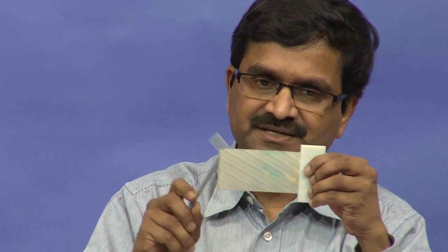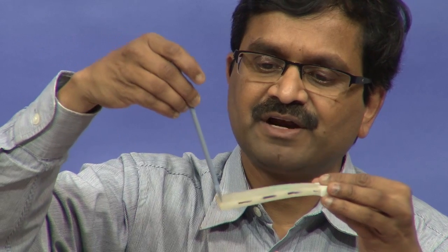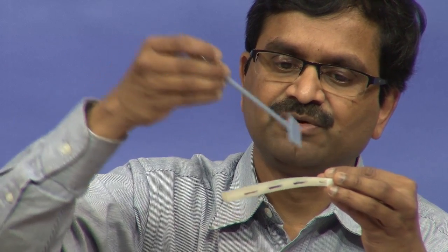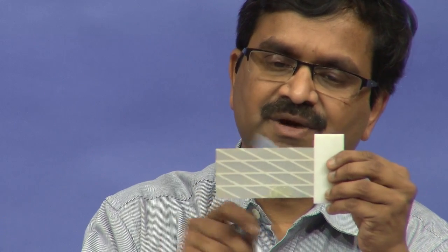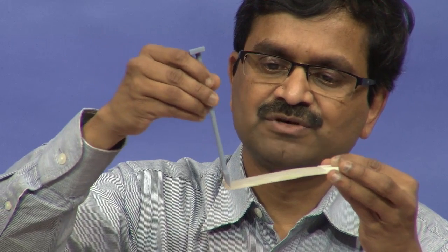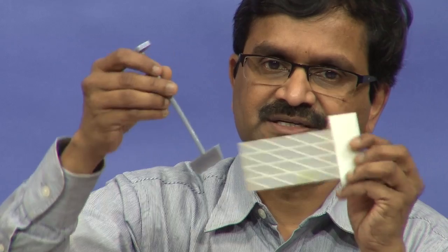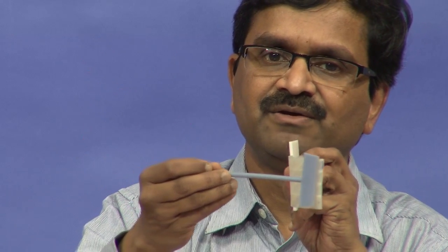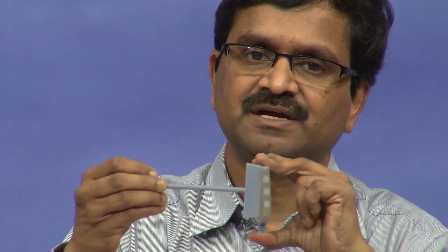Instead, if I make another one here, you again see some streaks, there are basically holes there. We 3D printed it with one material with holes. This particular one, when I do it, you do not see twisting, even though you have the same nature, the anisotropy is not dominant here. There is one more which has fiber-like things printed into it. Now, if I apply a force, there is a little bit of twist, but you can't see it. If I keep it like this and apply force, you only see bending, there is no twisting like we saw with this other one. So, this one very dramatically showed the twisting.